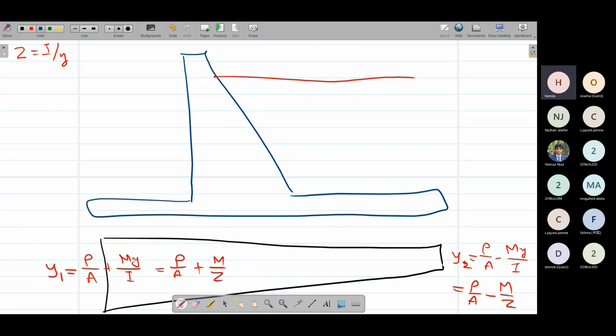So now we have to determine where the resultant force is acting, where this P is acting. For example, if we put this like this, that P is acting here. Now we have to determine its length from this outermost portion, from the base of the toe, that would be our X, and its length from the center of the base.